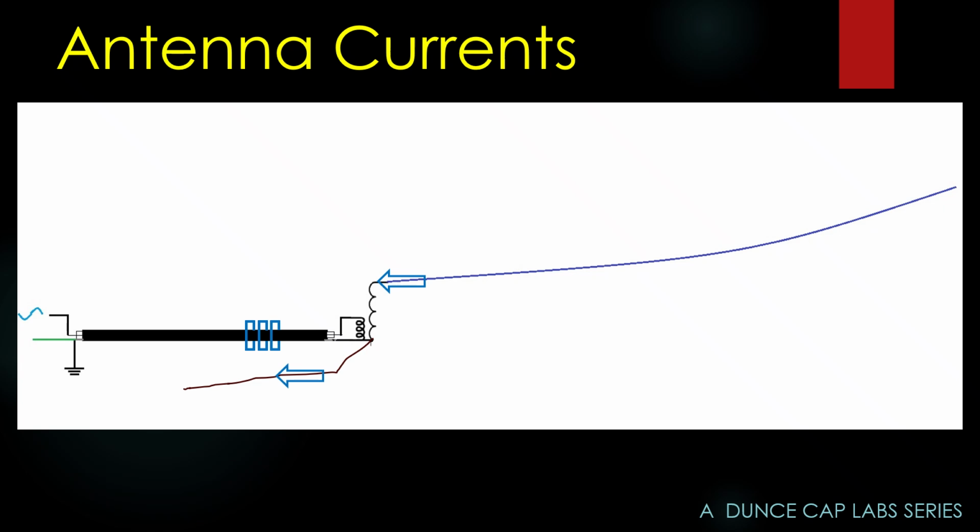Now, this counterpoise wire we just laid out does try to radiate a little bit, but the point is we're giving the secondary coil somewhere to suck and deposit electrons through the sine wave cycle. It doesn't matter that our counterpoise wire is a quarter wave long and our big wire is like 2 wavelengths long. That's not a problem. We just need at least a quarter wavelength piece of wire to sink and source electrons when the current flows.